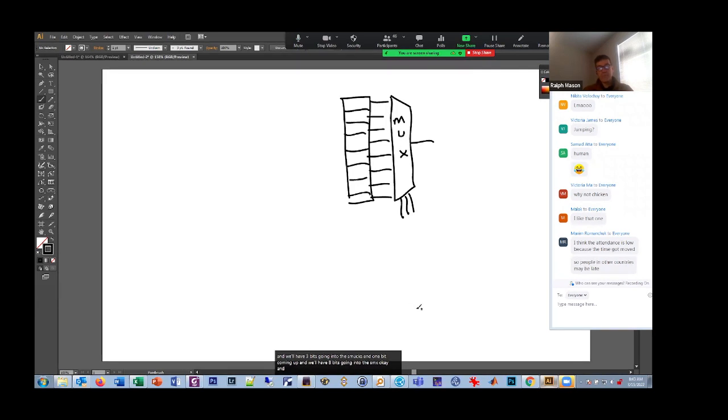Okay. And let's say we wanted to make a 3-input NAND gate. If you were to make a 3-input NAND gate, and we looked at the possibilities here from 0, 0, 0, 0, 0, 1, all the way up to 1, 1, 1, you would say for a 3-input NAND gate, the only time we get a 0 is 1, 1, 1. Any other combination of the inputs will give us a 1.